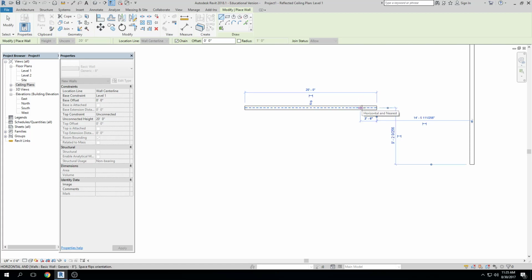All right. Now by doing that, again, the default unit in Revit is the foot, and so it's going to create a 20-foot long wall, as opposed to 20 inches, which is what we get used to in AutoCAD. When I work in AutoCAD, and it's just me, I tend to work in inches. You know, I think 10 feet, that's 120 inches, right? So I just type that in, but you have to get used to working just a little bit differently. It's the same thing, just kind of opposite, right?